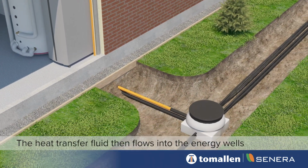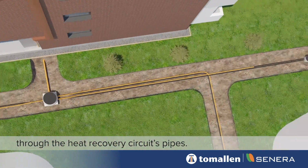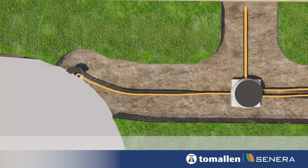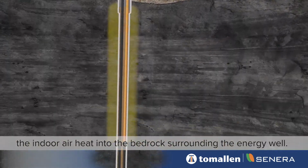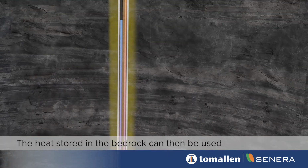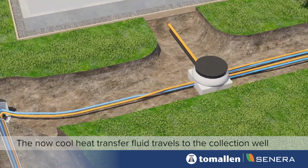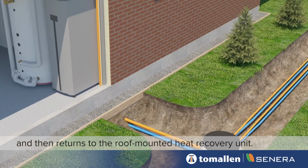The heat transfer fluid then flows into the energy wells through the heat recovery circuit's pipes. In the energy well, the heat transfer fluid transfers the indoor air heat into the bedrock surrounding the energy well. The heat stored in the bedrock can then be used during the next heating season. The now cool heat transfer fluid travels to the collection well and then returns to the roof-mounted heat recovery unit.